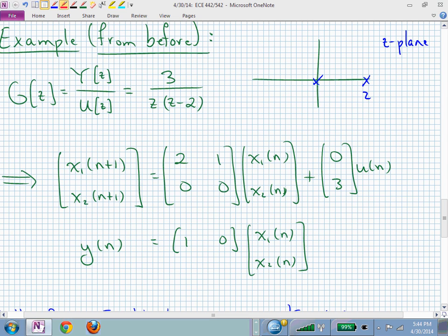So now, because it's two poles, it's going to split right equidistant between those. One's going to go up, and that's all supposed to be on the real axis. I for some reason couldn't sketch it properly. One's going to go up, one's going to go down, plus and minus 90. They're intersecting right at 1.